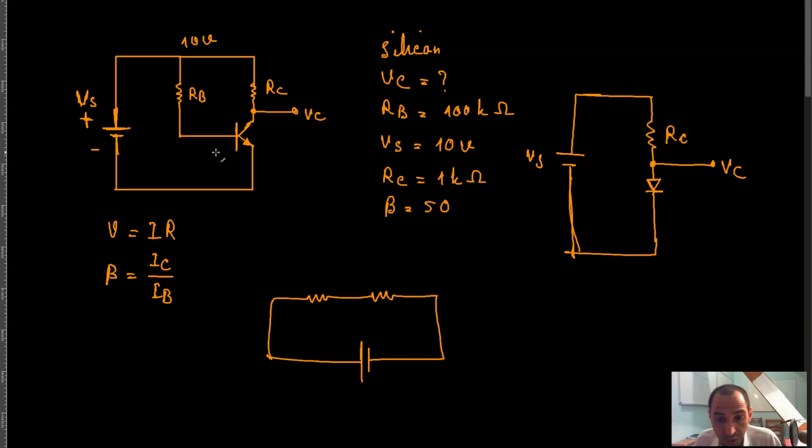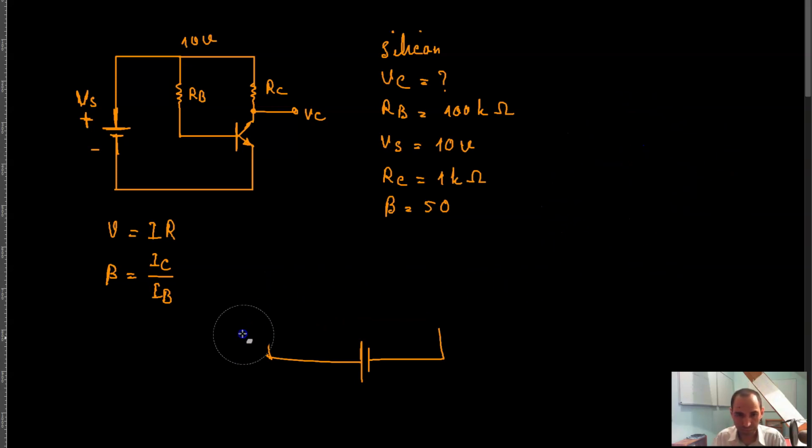So that's the beauty of these transistors, and that's basically how wonderful a type of device they are. Now, in order to calculate, for example, the V of C in this circuit, as we discussed here, first I need to calculate the base current. Once I know the base current, I put it in this equation, and as a result I will be able to calculate the collector current.